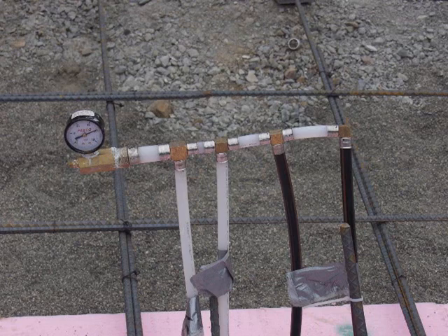I would always start at the fittings right here where we've set up our control gauge, and then if you do have any joints in the slab, those would be the next place to investigate. After that, you're just going to have to run up and down the tubing with some soapy water to try to find any leaks in the lines. It's very unusual for this tubing to have leaks in it, so if there is any kind of loss of pressure, it's most likely going to be at the fittings, and you'll just need to do a better job of crimping them together.